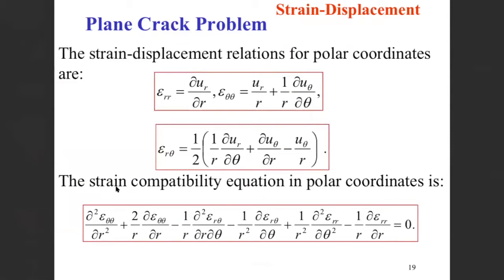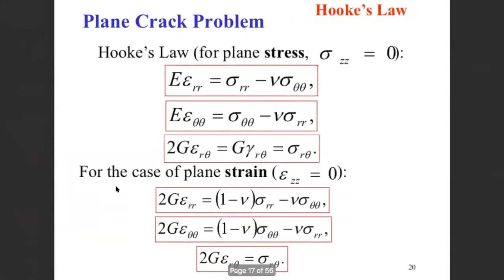Anytime we start with a classical elasticity problem, we start from these basic steps. Stress equilibrium has to be true. Compatibility means, with the exception of the crack that we're doing the analysis around, we're not overlapping material points, we're not mapping two material points to the same point, we're not opening any holes, and points that are infinitely close before the deformation remain infinitesimally close after the deformation. That's what the strain compatibility equations guarantee.